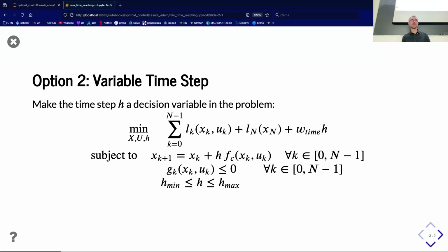You could also decrease h max. Yeah, but if the solver has found a solution that is 50 milliseconds, and that's a solution that minimizes h, and you set h max to be smaller than that, you made the problem unfeasible. So you didn't solve the issue.